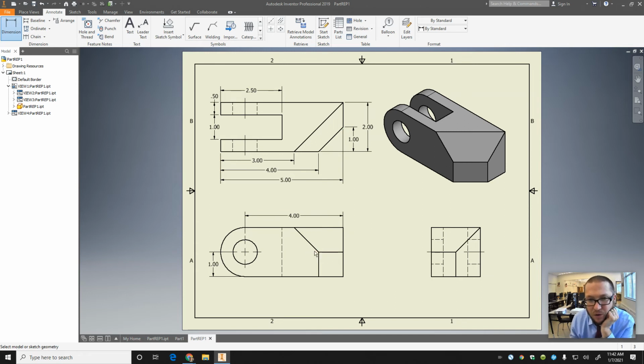So let's look in this drawing. I know this thickness, this must be 1 inch right here. I know this location has to be 1 inch here. What I don't know is this height. I don't know this height from this view. I'm going to guess it's 1 inch, right? It must be. And technically, maybe I do know it because this line's up here. I guess technically I don't know the overall height this way either.